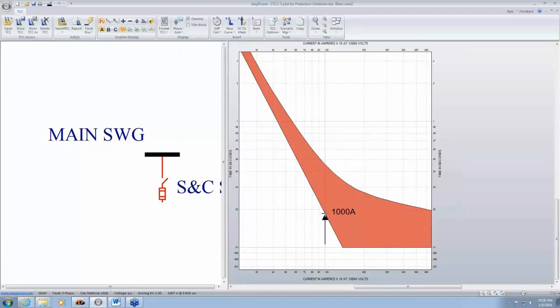So there is an indicator here at the bottom. I'm going to take my cursor there. See this? Just keep your eyes out at this section and you'll read the coordinates there. Based on the cursor position, I can read my coordinates. So this is saying approximately at 1000 amps, I'm getting 0.019. So in approximately 19 milliseconds, the fuse will start to melt. That's how we read it.